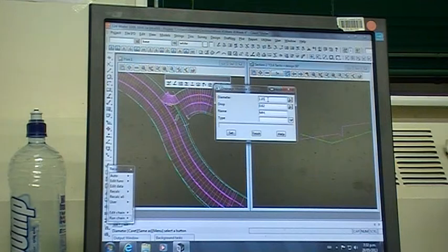So we always refer to them in terms of internal diameter. The reasons for going to bigger, any idea why we go to bigger manholes than a 1050? Sizes. Bigger, if there will be a point where pipes coming in and out of the manhole are so big that you have to increase the size of the manhole to allow for that.